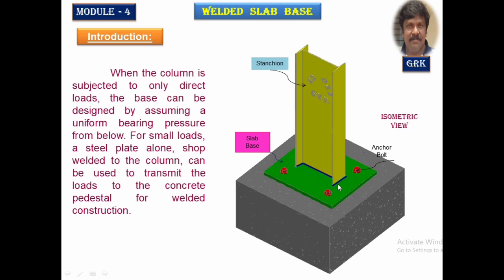If this end is cut by machine, also called ground ends, milled ends or flushed ends, then we are going to take 50% of this load for designing the welding.